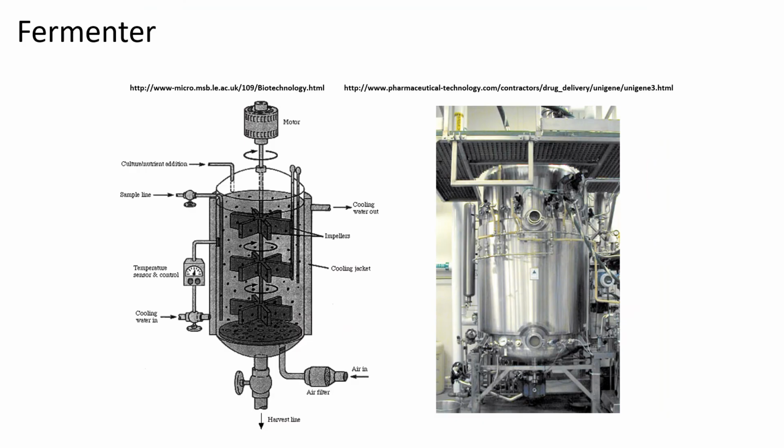I want to briefly just talk about the fermenter and its design. What's shown here is a cartoon, a diagram of it. And over here is an actual physical device that was constructed. Typically, these devices are made of stainless steel like this, especially in the pharmaceutical industry. But if you were to look inside here, what you see is just a giant open cylinder, into which there's this shaft that comes down, and to the shaft are attached blades, and the shaft rotates to mix the fluid up in here and try to achieve a uniform concentration.